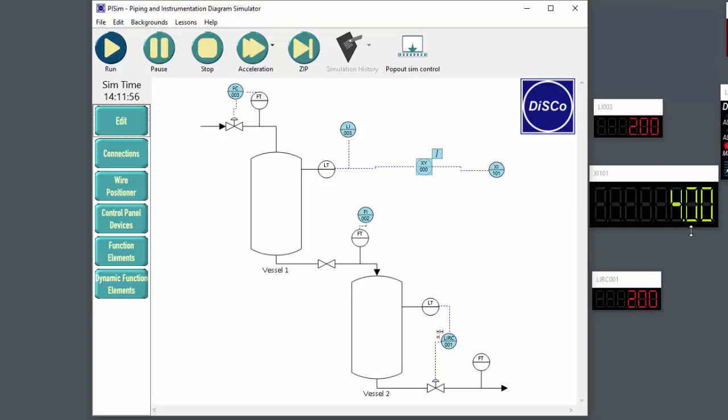Okay, so he's starting at 0, 2, 4, 6, 8, 10, 12. It's just integrating it with a 1 second sample time, so the delta t is 1 second. So obviously you can use this integrator for all sorts of things. You could calculate ISE, I guess. You could use it as part of some weird wonderful control scheme. I have no idea why you would use the integrator in a control scheme like that, but I guess you could if you wanted to. But it's there if you want to use it.